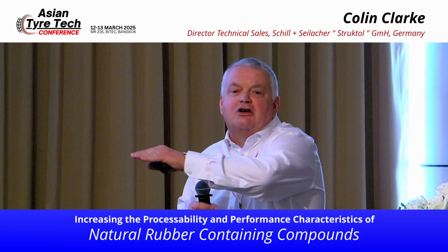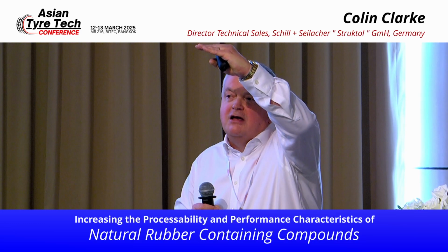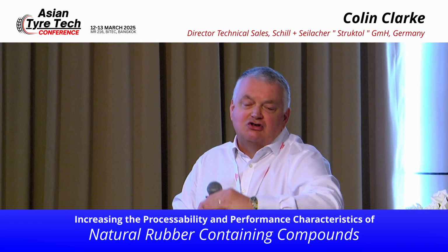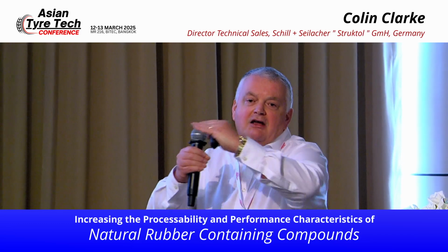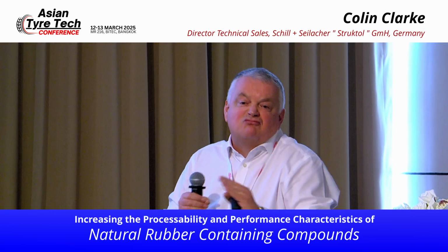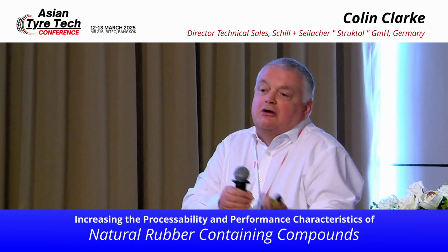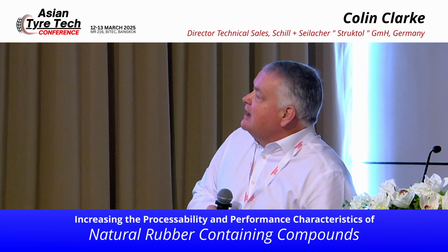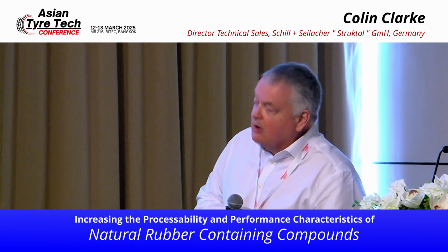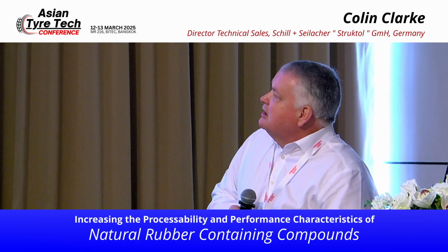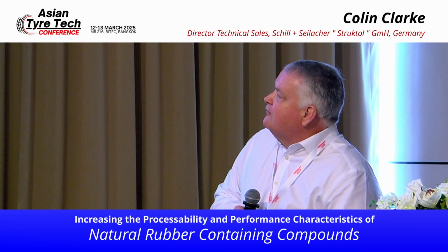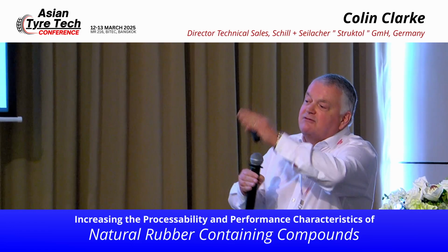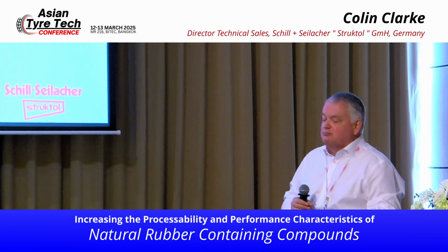But if you remember the energy curves, mechanical mastication was very high, the new peptizer was very low energy. So we have a breakdown that looks like a chemical peptizer, but a molecular weight that looks like no peptizer. So this is already a good sign for good processing and good properties. This is really the best of both worlds a little bit. And actually we can confirm that because when we finally look at Mooney viscosity, chemical peptizer and HT105, exactly the same, but dynamic properties or molecular weight, if you like, looks like no peptizer present.